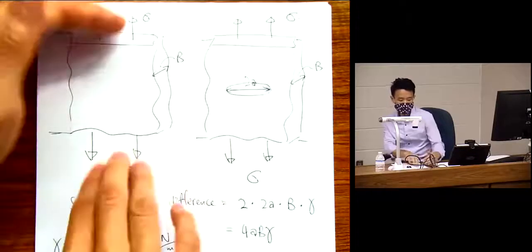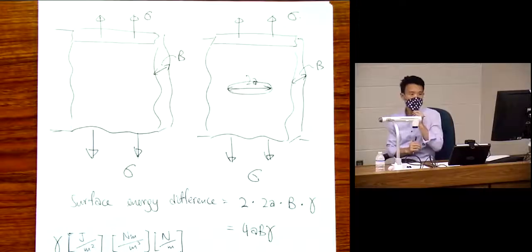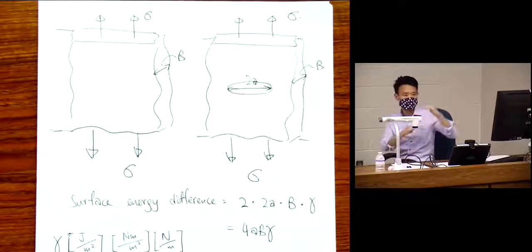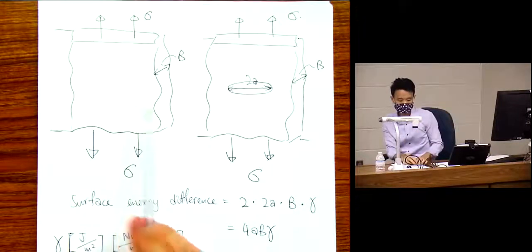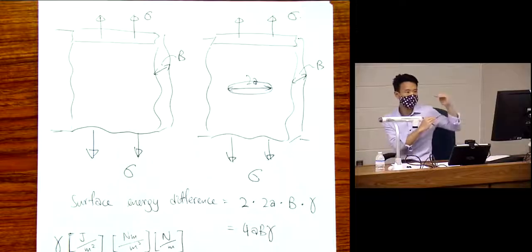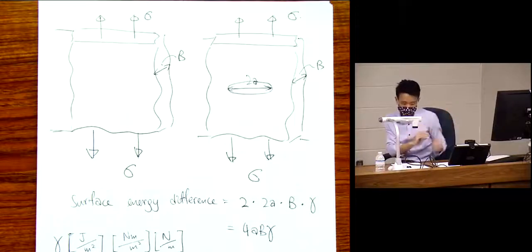So if I go from this configuration to this configuration, there's not going to be any more external work done. Even though there's a stress, there's no work done because I stopped the grips. Work done is the stress multiplied by the displacement, and in between these two there's no difference because the grips have stopped. We make them stop, right? We don't want any work done.